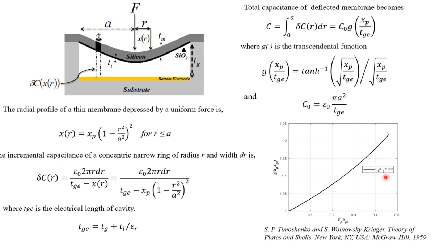Because this means that the device is in vacuum, the only force that is depressing and making the profile as such is the electrical force. You don't have ambient force. But if, let's say, the Fg is like 0.9, that means the ambient force is like 90% of the force required to collapse the membrane. In that case, the curve can start from like 2 or 2.2, and it might grow more than 2.4, 2.5.